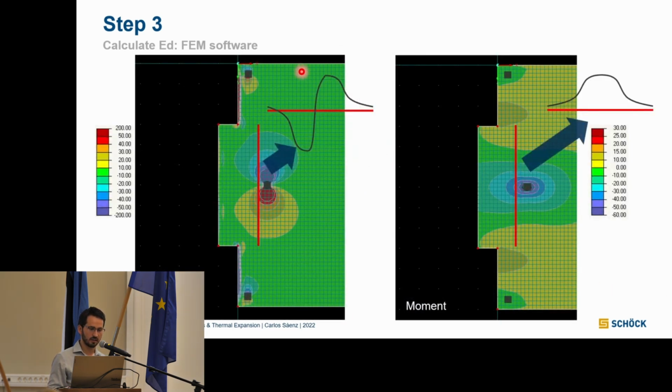Because actually here, the designer modeled the whole slab, all the inner slab, with the balcony as a piece, as a monolithic, both together. And this is where the problem is, because he modeled everything and just passed the line here where my connection, with my thermal break, is supposed to be.